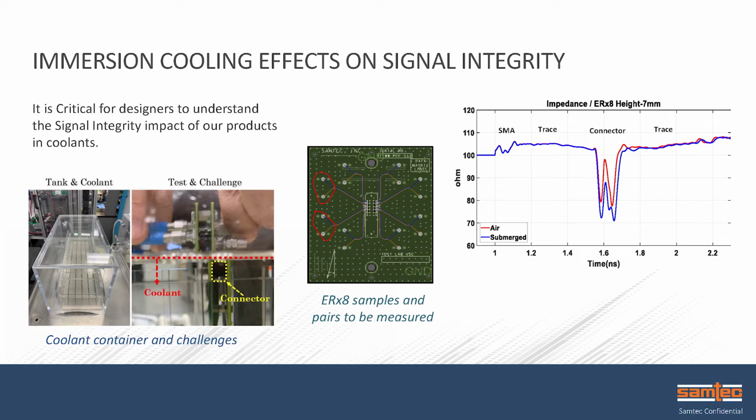This will be critical for you to understand because most connectors are designed with an air dielectric inside the connectors in the mating interface. Now if we put this in an immersion cooling tank, we've changed the dielectric constant, which can now affect the signal integrity.